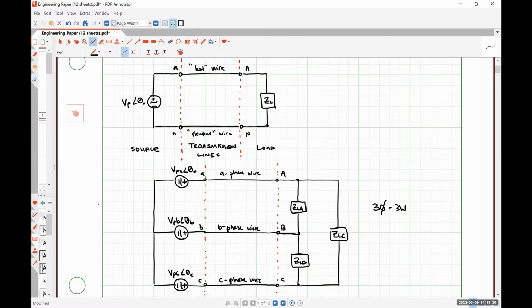So if we have a rotating magnetic field with a constant amplitude, what we find is that we have a constant rotational torque when applied to a three-phase motor, which means that the amount of power that's delivered to a three-phase motor is effectively constant, or at least the amount of average power that's still delivered to a three-phase motor is effectively constant, which in turn means that the machine will experience the least amount of vibrations and therefore undergo the least amount of mechanical strain and wear and tear when it's served by a three-phase system.